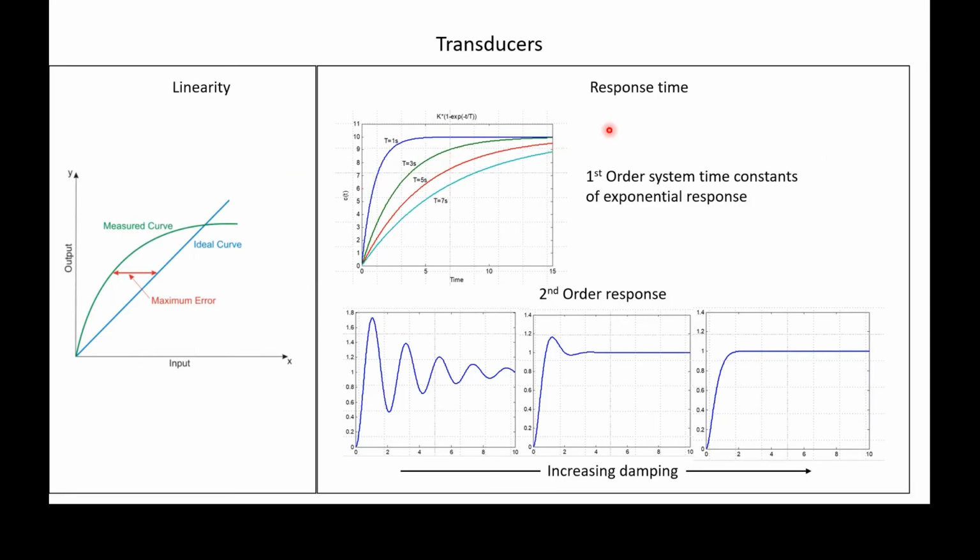But talking about the way that the transducer would respond to a step change, we would see that depending upon how good it is at the high frequency components of your signal, it will either respond very quickly and be almost a square, or respond rather sluggishly.